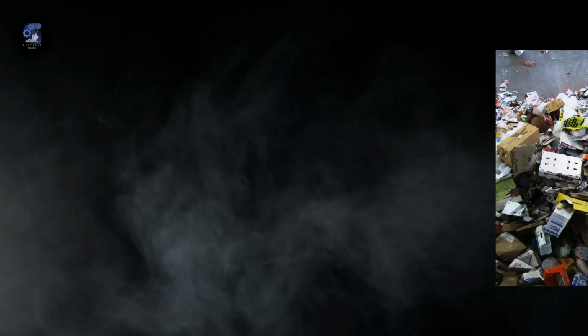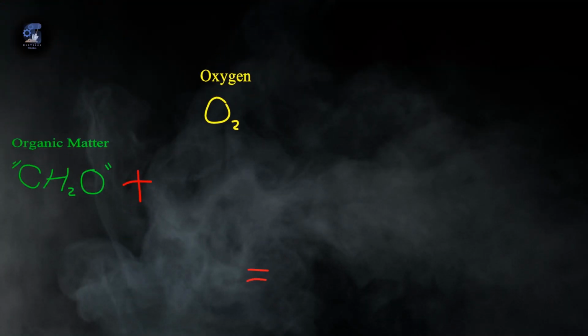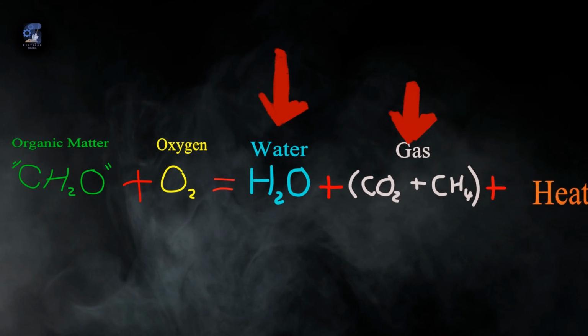You see, unlike soil, the waste matrix is comprised of different constituents of different individual properties. Remember, municipal solid waste is a collection of household garbage, construction waste, and non-toxic industrial waste. For example, the decomposition of organic materials has an adverse effect on the stability of the landfills. When organic matter decomposes, water and gas are released as a byproduct of the process. This process is neither linear with time nor constant across all different organic materials. This means it is difficult to accurately predict the long-term mechanical behavior like settlement and shear strength with the same ease that we can predict that of soil.